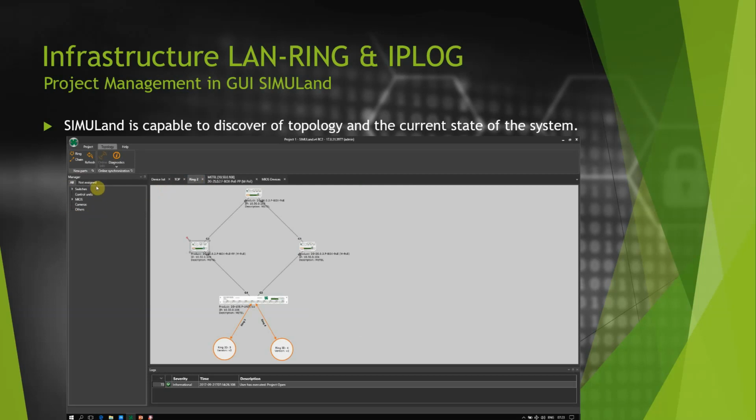On the left-hand side of the screen, there's a manager for organizing objects in the work areas. Under the All tab, all the elements that are included in the project can be found. Under Unassigned can be found all the objects contained in the project, but not assigned to any of the work areas. So if the project contains, for example, a switch with older firmware without LLDP protocol, it will be included there, from which it is possible to drag it to any position.